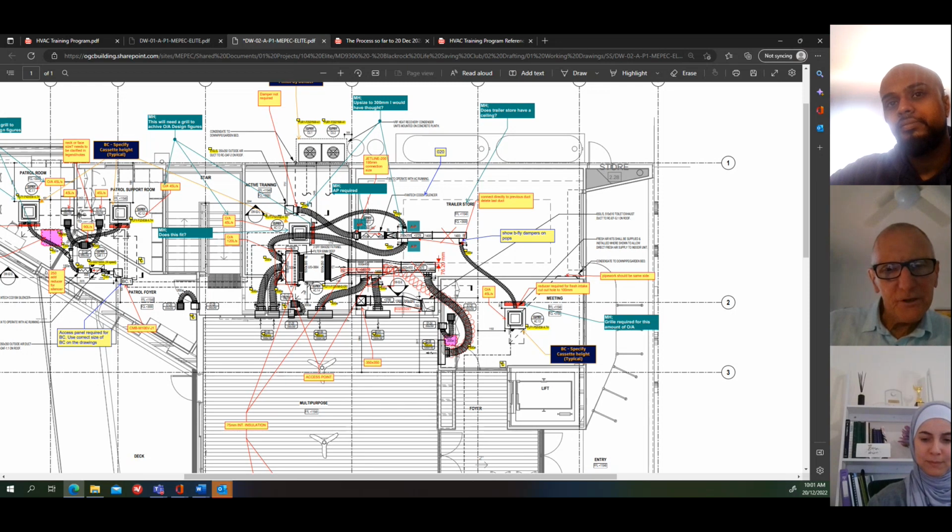And that's one of the reasons I say if you can get the plumber to put a tundish very close to the air conditioning unit, then it's not our concern anymore. We get the pipe to the tundish and we're okay. But if we have to run the tundish a long way, then we've got to be very careful. Well, the guys on site have to do it. I mean, it's not an engineering design thing.